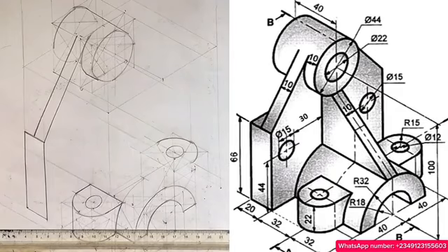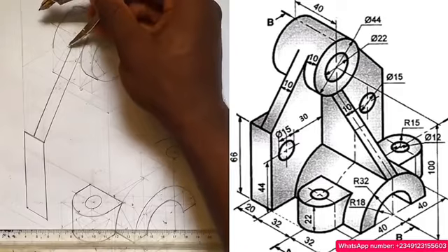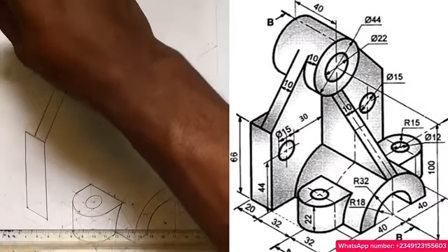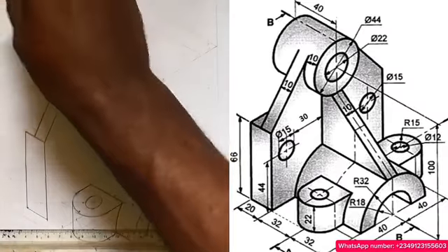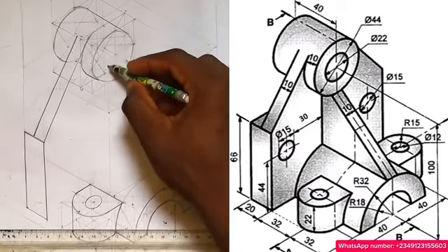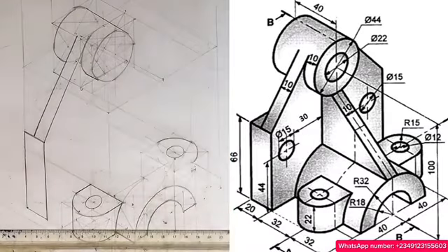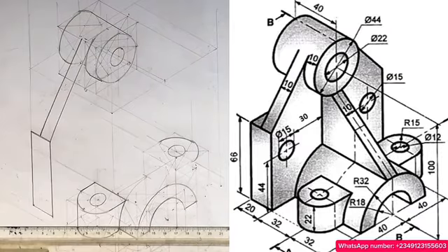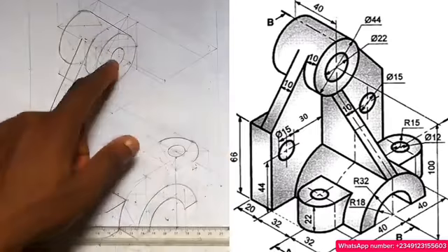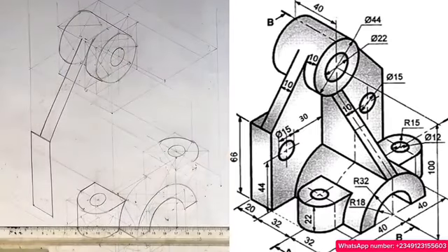Next task is to come back to this point and thicken this arc well, because I've seen what I want to use now. This point this way, right? So I have what you're seeing there. So there's a curve inner here, and the curve is given to be what? Diameter of 22, so that's 11. So I'll use my French curve, this one here, to draw the curve, right? So I've done the curve there, so I have to save time.